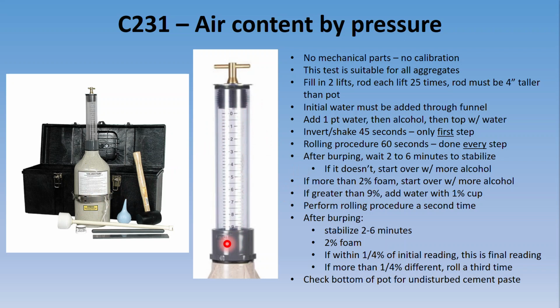But we're going to assume everything's tight, your gaskets are good. You just have a lot of air. If that's the case, and he doesn't talk about this much in the video, you have to add more water back into this so you can bring the water level up into a portion of your scale that you can read. And you do that with this little cup down here, right? And this cup represents 1% of the volume of this pot.